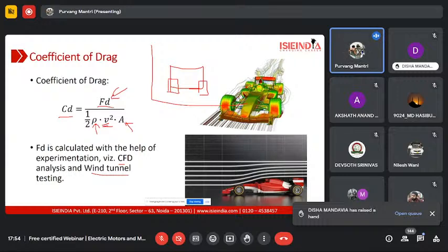So yeah, here's the thing. You click a picture of the frontal portion, from the front side of your vehicle, so that the front view gets on the picture. You print it out, and at this point you can get the wheel track from the specifications provided by the manufacturer. It will be provided in the owner's manual, and from that just measure the distance between the front wheels in the image. With that dimension and the dimension of the wheel track provided by the manufacturer, you can get the scale of the image.